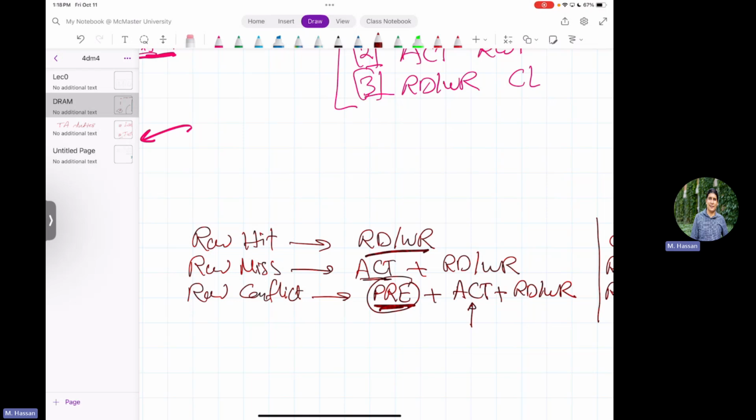DRAMs are in fact controlled and organized by an industry standard called the JEDEC standard. This standard is basically a consortium of different industry and academic participants, all of the manufacturers of DRAM and CPUs, etc. They come together, for example, to work on DDR5, which is already on the market, and DDR6, which is coming in 3-4 years. They are now working on finalizing the standard for DDR6. They sit together and discuss what the technology challenges and changes are from DDR5, how it works, what the timing constraints are, and whether they can have an early manufactured chip to study how it works, and they come up with this standard.